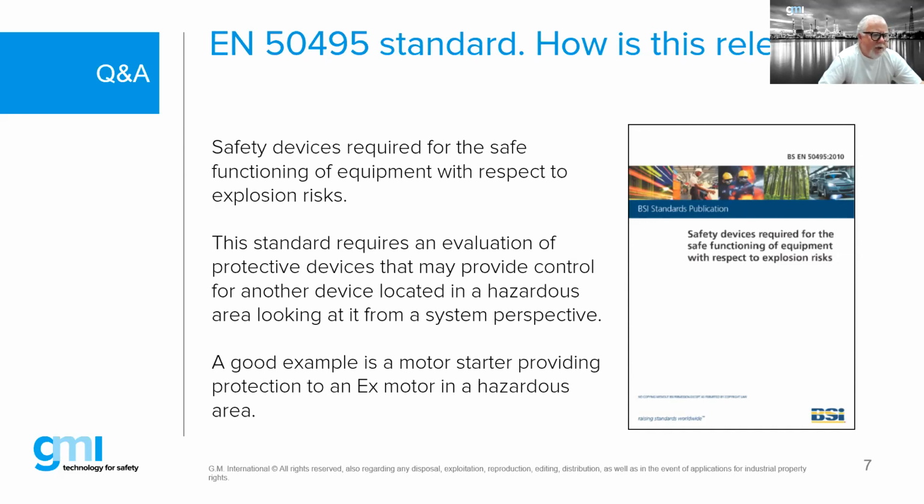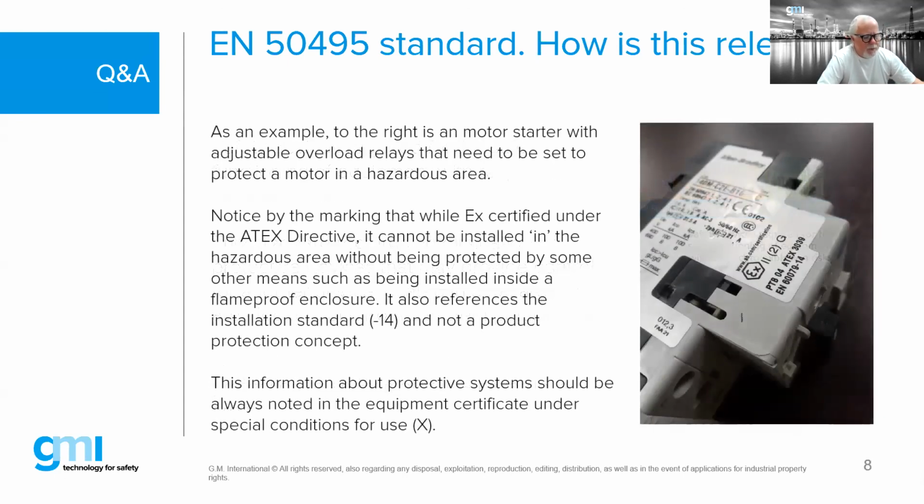And are we making sure that the trip settings on, say, for example, our contactor are set appropriately for the motor to make sure we take it offline so it doesn't overheat and potentially create an explosive hazard? That's one example. There are other ones as well.